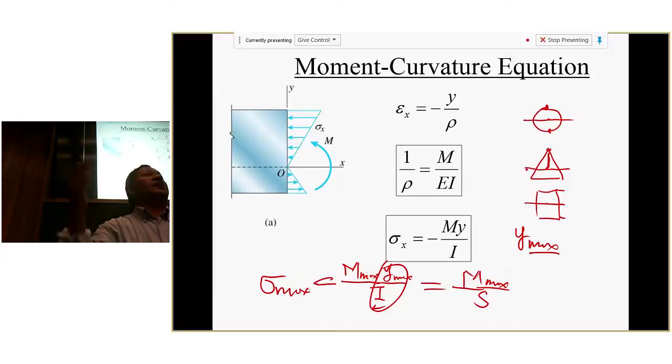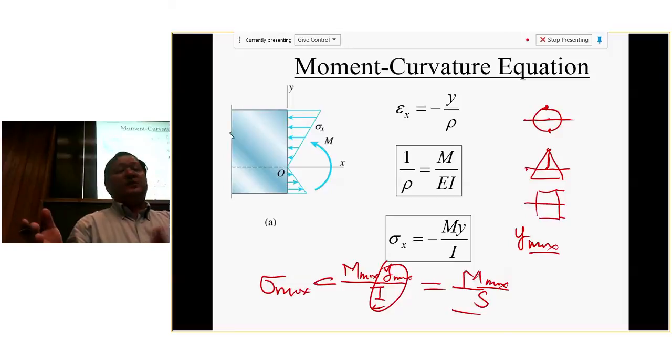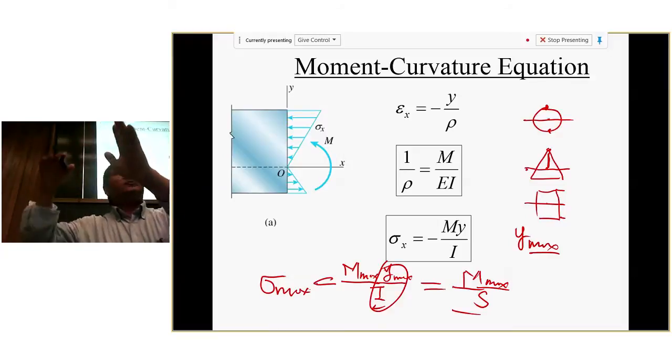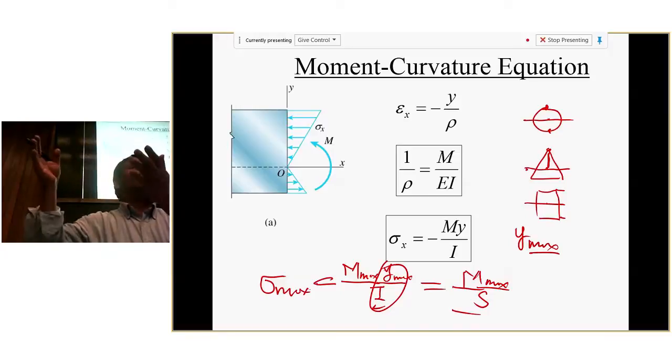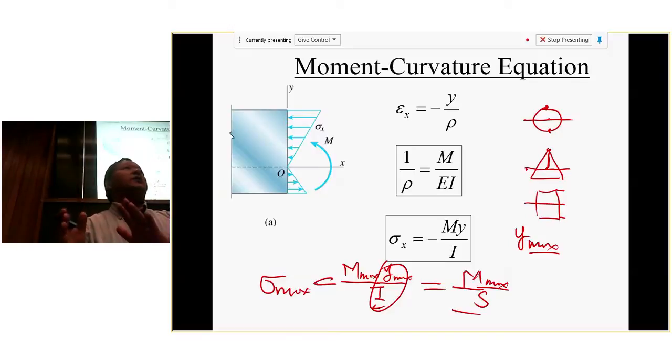So when you do the calculation for maximum stress, it's much easier. You just use this equation, right? So just simplify one step. Fundamentally, it's the same thing, right? You put the y maximum there, you put the I value there, but just one step easier. And in the textbook and engineering manual, for a given cross-sectional shape, an I-beam or rectangular beam or circular beam, you can always find the I value, and also the S value. So you can just directly use the S value to calculate.